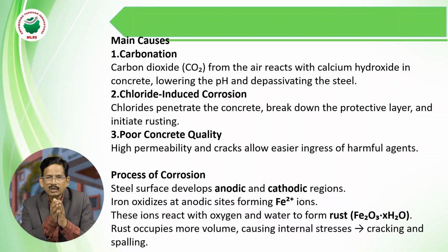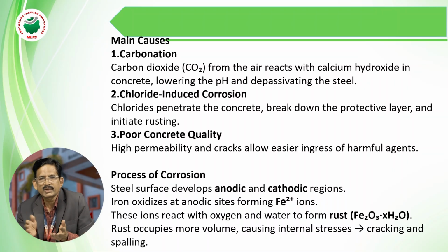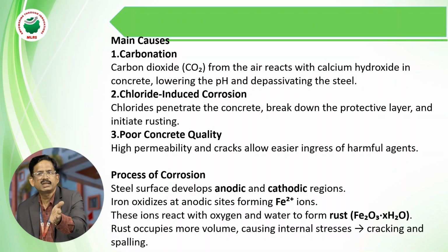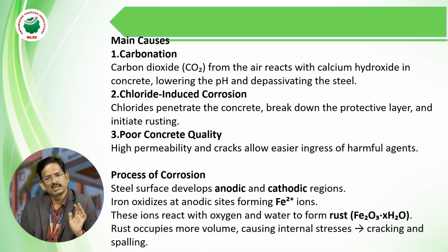That's why we are always thinking about the good quality of the concrete. That's why we test it in the laboratory: compressive strength with the help of the cubes, flexural strength with the help of the beams, and split tensile strength with the help of the cylinders also. Why are we going to test it? Sometimes we test it at 7 days, 14 days, 21 days, and 28 days also.